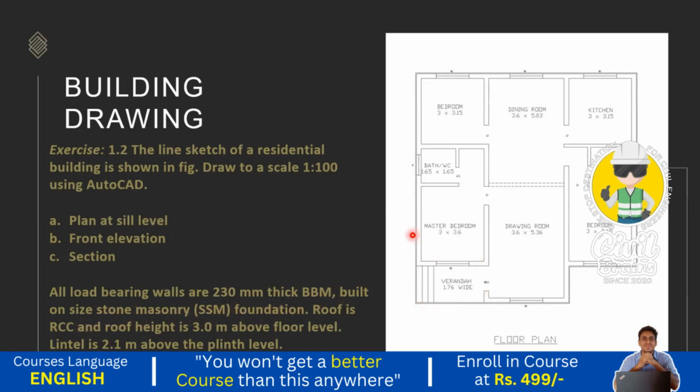Okay, so whatever the plan is here, this plan is at sill level. What is meant by sill level? The bottom of the window level, that level we can consider as sill level. So the plan at sill level we need to draw, the front elevation we need to draw, and we need to draw the section.